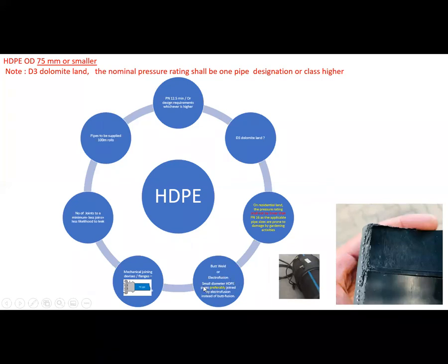And then I just want to make a note here, or you should just try and make a note on your side maybe: small diameter pipes must preferably be joined by electrofusion instead of butt fusion. The picture on the right is showing the electrofusion, where they put a charge in, it heats it up, and it seals, and it almost welds the pipes together. The picture on the right-hand side is where I'm holding a section that has been electrofused, and you can see those little points, the little coils on the left-hand side.